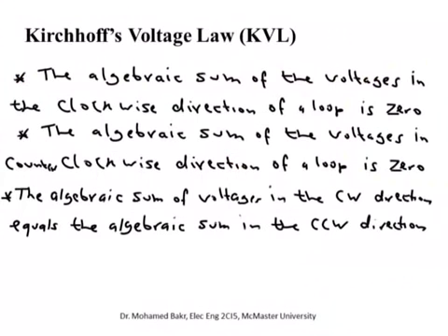Okay, the second law, the second important law for us is called KVL. KVL can again be applied in 3 different ways. They are all identical. They give you a difference of a negative sign, or you can move some of the terms to the other side, but they all give you the same equation. The first one tells you, okay, you go around a loop, any loop, in the clockwise direction, and you sum the voltages, you must get 0.